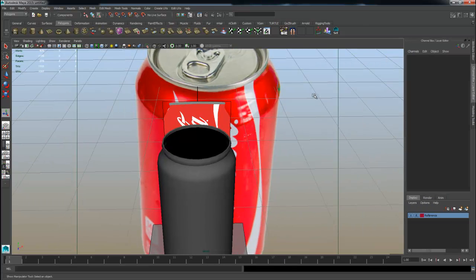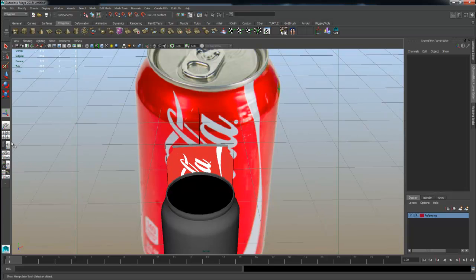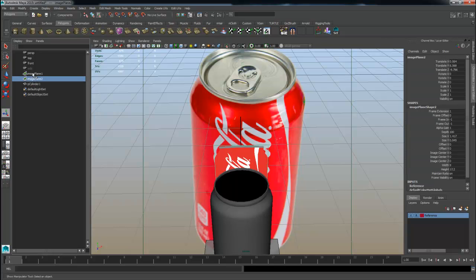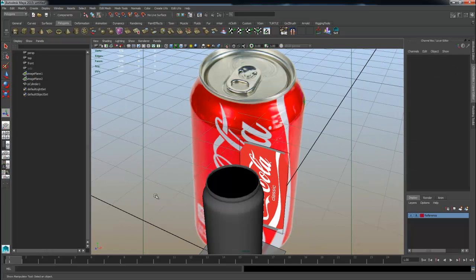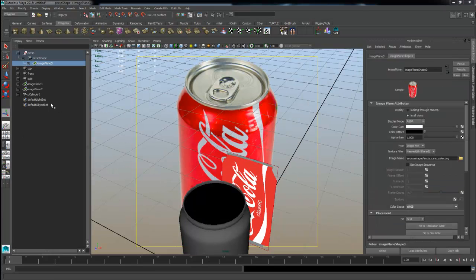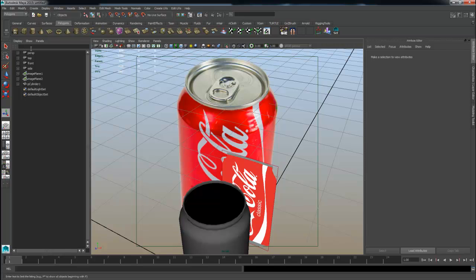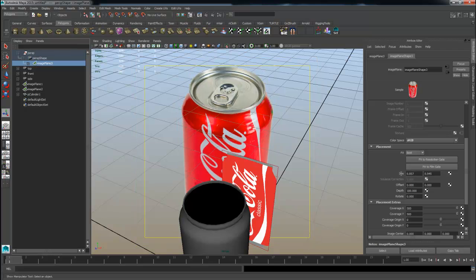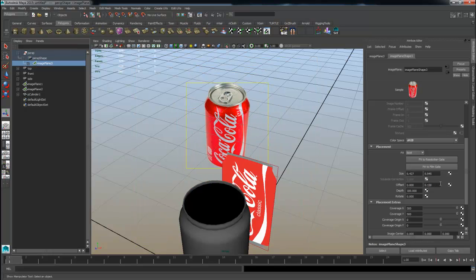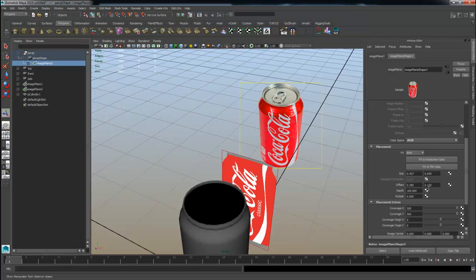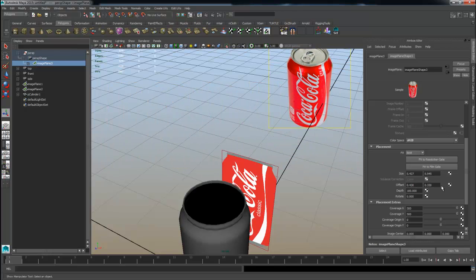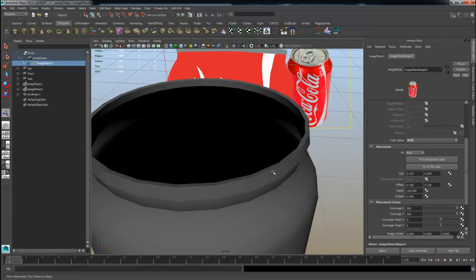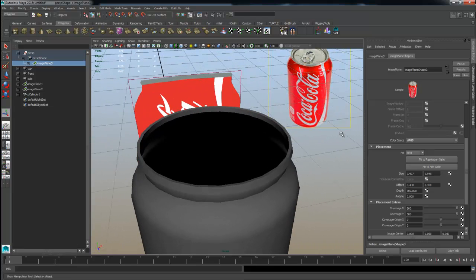So what I need to do now is just scale it down, get it to line up with the corner of my perspective, so it's more used as a reference instead of right in the dead center. So that image plane selected, and then under the perspective drop down menu, have that selected. I'll be going into its properties, and under the size I'm going to hold down Control and click inside of those little boxes, and that's going to allow me to interactively move the position of that image plane. Once I'm happy with that, I'm going to use that to profile out the inner details.